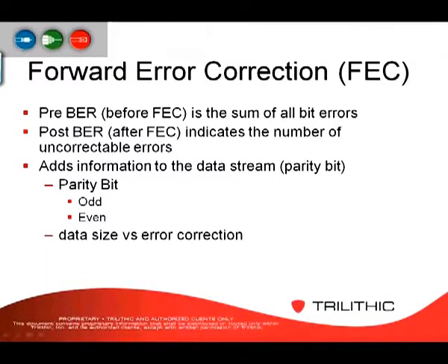Now, pre and post forward error correction measurements. QAM communication systems include the means to patch up some of the bits that become corrupted in a transmission, and that's what the forward error correction does. The forward error correction data included with the QAM data transmission is the information the QAM receiver, or your digital set-tops, use to fix the misinterpreted bits.